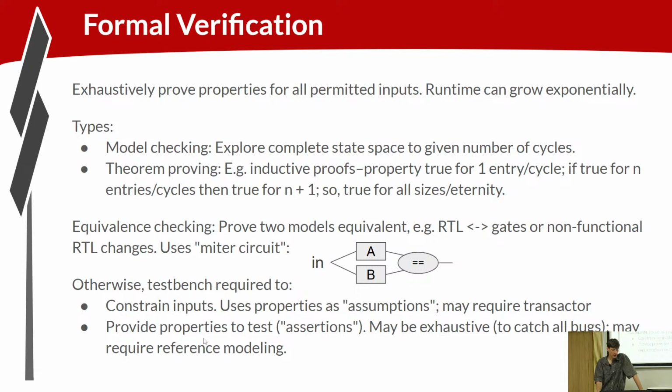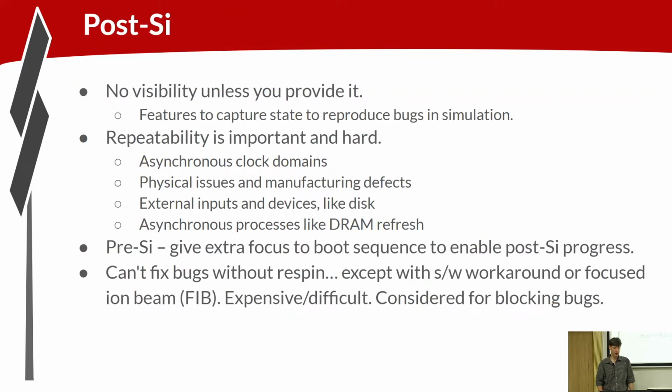And then similarly on the output side, it might be essentially necessary to create a reference model to define the assertions that you're looking for at the output, where the reference model is modeling the behavior that you expect, so that you have a reference to compare against to create the properties that you're checking at the output, right? So depending on the nature of the model, there can certainly be a fair amount of work on the verification modeling around the formal verification effort. Basically just to say it's not free.